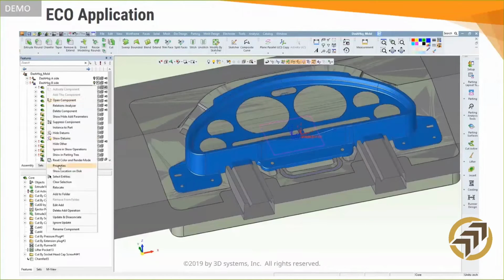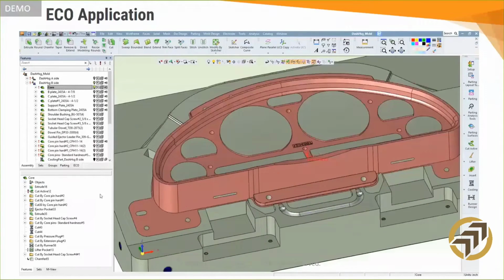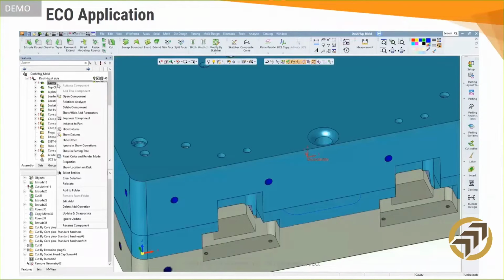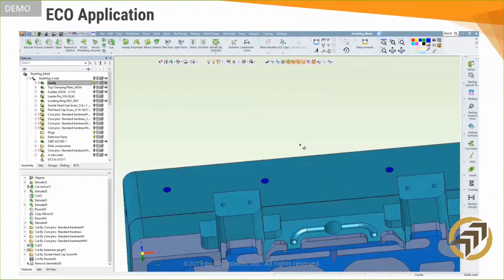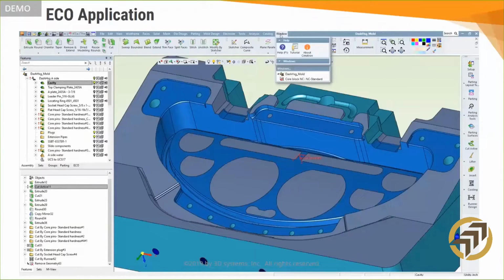The cavities, cores, and other inserts in the mold then fall in line for updating. The parametric and associative nature of Cimatron features means that even if the change has created a conflict in a mold component, the user can pause the action and adjust the design as needed. Real changes require real decisions and often new components, but Cimatron eases the burden by sorting and passing the new data to exactly the places you need it to make those decisions.